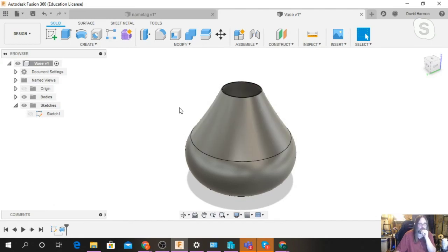And the STL files, and Greg mentioned it in the Tinkercad video too, but STL files are built up of triangles. Thousands and thousands of triangles. So when you actually see your shape in Fusion here, and we have those curves, it's actually building tiny triangles to build all those curves. And sometimes, no matter what you do, you'll get a model and it will have an error in it. Your slicer will warn you too, and we're going to talk about slicer errors next time, but just mentioning it now. So if the error does occur, one of the biggest features of 3D Builder is repair.